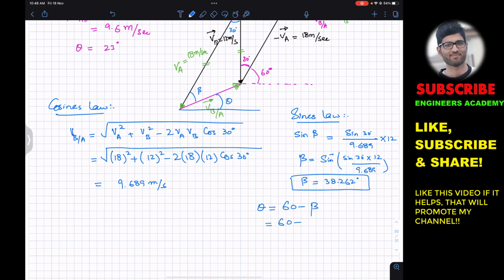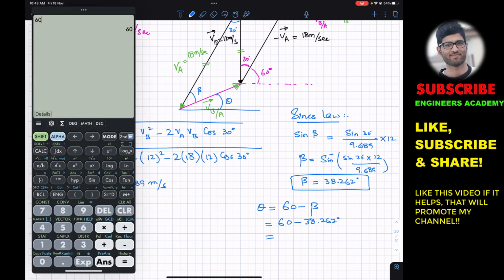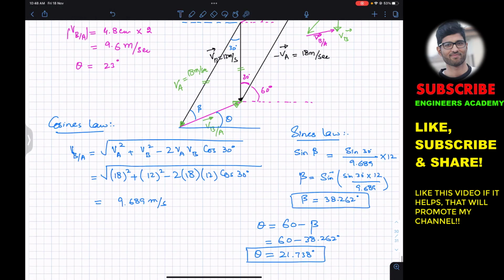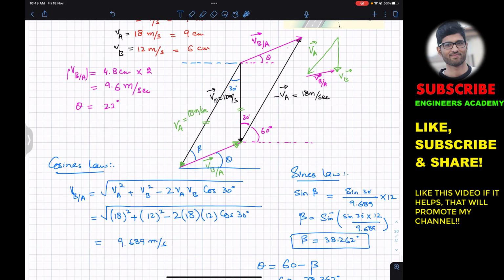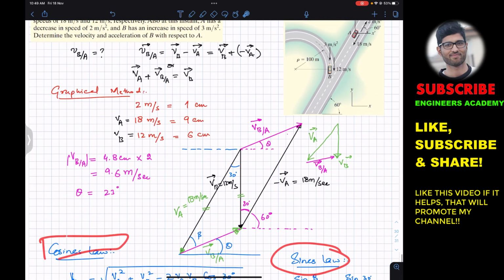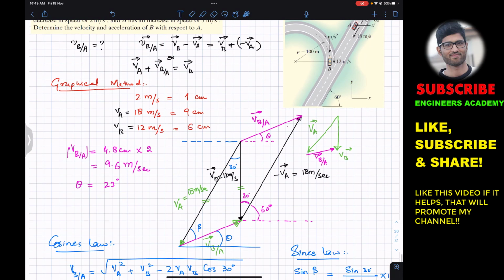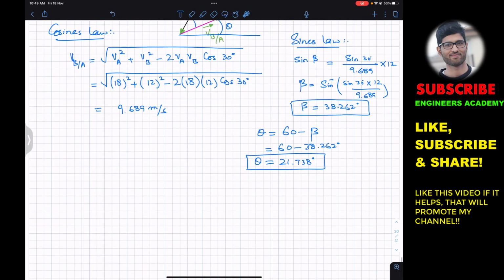So 60 minus beta, which is 38.262, this is equal to 60 minus 38.262. This is equal to 21.738 degrees. So the angle is also approximately equal to this angle. We will most probably use the cosines law and sines law, but we need to know how to implement these equations. So this is how we can find the velocities using the graphical method. For the acceleration, we can find it using the same graphical method.